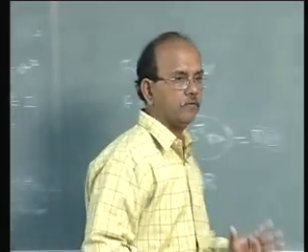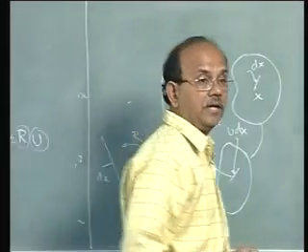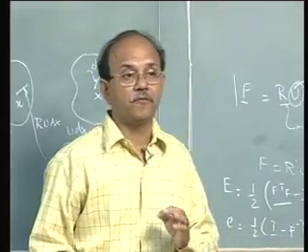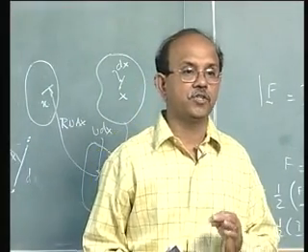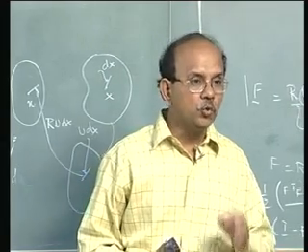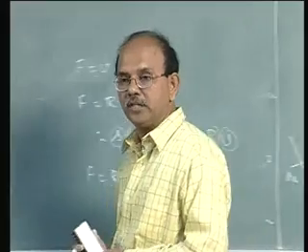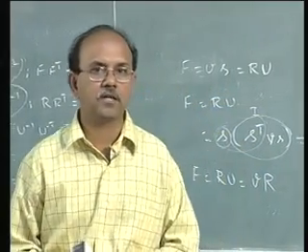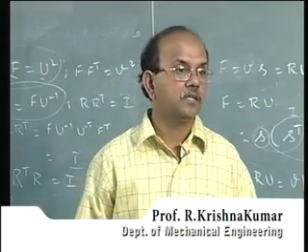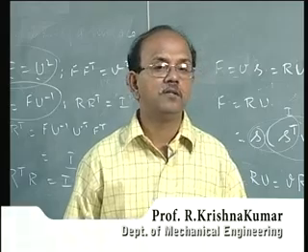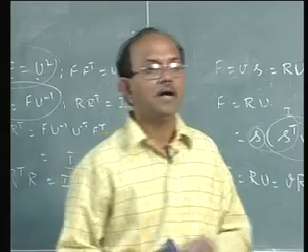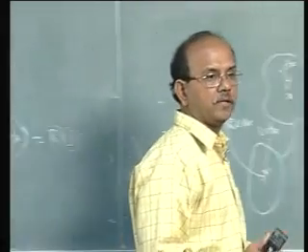Note that again this is different from the decomposition you would have done for u i comma j in the small strain case. We are going to see an equivalent of it maybe in this class or next class. If you remember u i comma j, you would split it up into a symmetric part and a skew symmetric part.